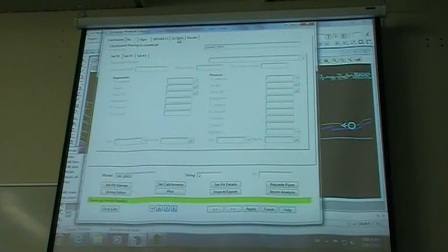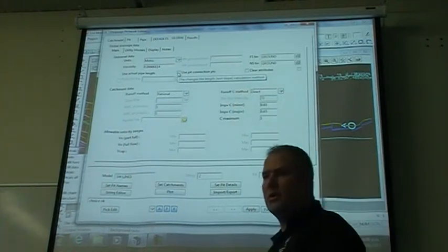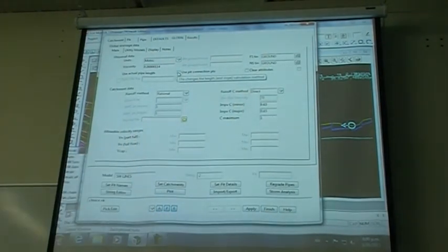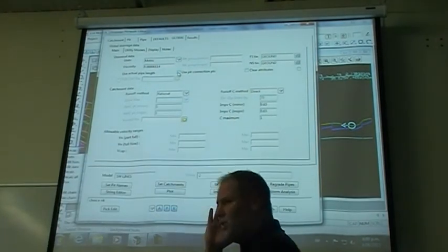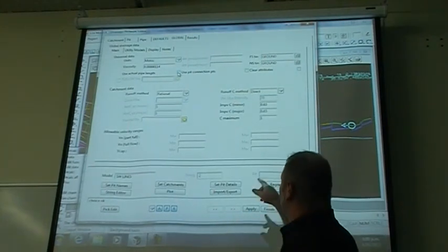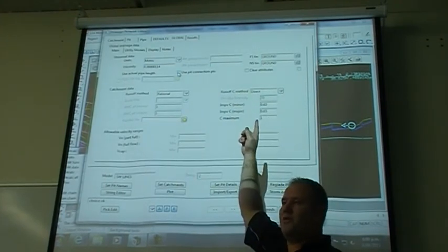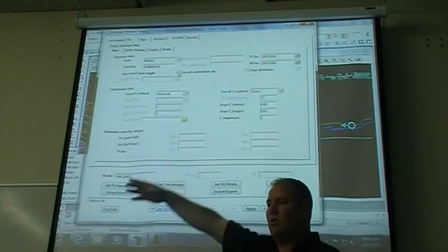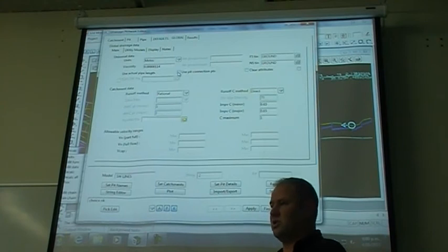So the first thing I'm going to do is click on my global tab. Now I did set most of this last week. I know you all had to look over my shoulder, so I apologise for that. But I'll just run through it again. For the purpose of this course, I don't want to get into breaking down the catchments too carefully. Anywhere that the network editor prompts you for a percentage, set them all to 0.65. Okay? Just to keep it nice and simple.